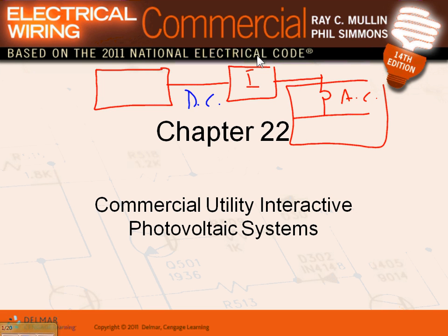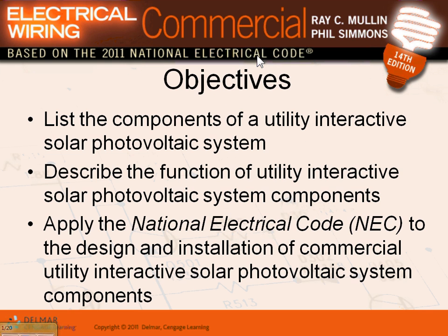This is my solar panel, and from the solar panel, you generate DC. I'll show you how we're going to calculate this. You can't tie DC to AC unless you want to see a big fat spark coming out. So you generate DC for the most part, you convert it into AC by inverting it, and you dump it into the grid so you can utilize it in different ways. That's really the whole photovoltaic system summarized. Cool? So let's go into the details in a second.